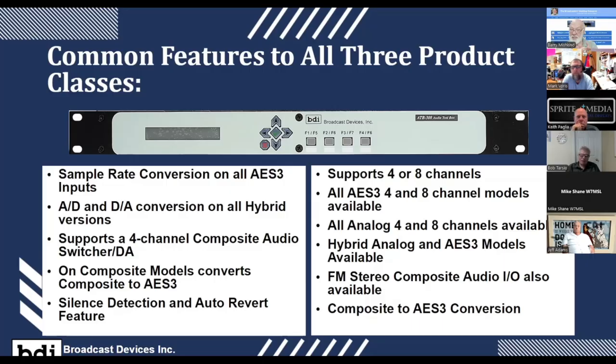On all analog models, the switching is all done in the DSP domain. We use synchronous switching to do AES switching, and even in the analog domain, all the decision making for the silence detector and auto revert is done in the DSP that we have on board. And we talked about the other 2 bullet items there, so I won't bore you with those again.